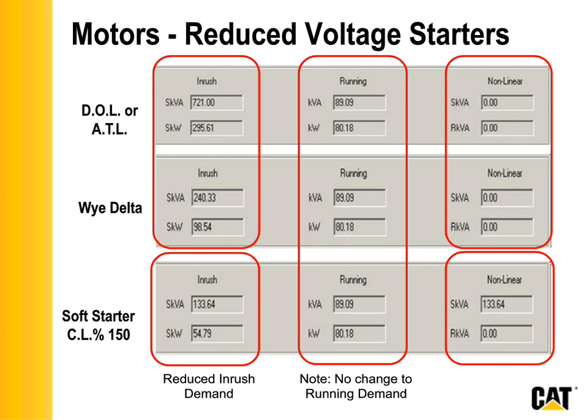Now, another tip, important thing to remember, is you can get a lot of benefit here with the soft starter and the VFD, VSD. But what you need to be aware of, usually it's not a big deal, but just be aware that the soft starter and the VFD, VSD, they create some additional harmonics and distortion. So, just be aware of that, you got a load there that's no longer linear, it becomes nonlinear. Okay, so your genset sizing will account for that.